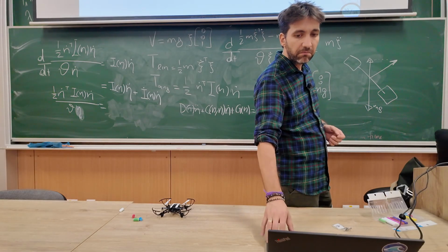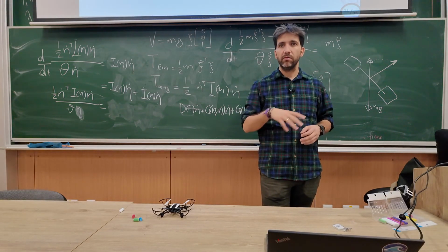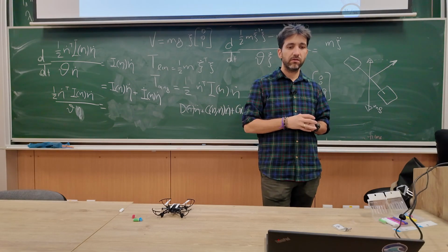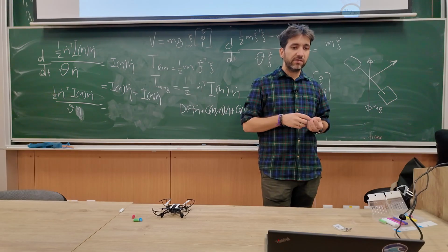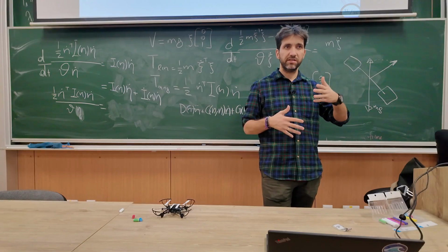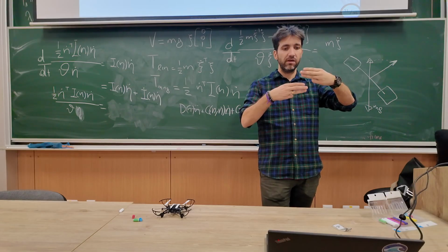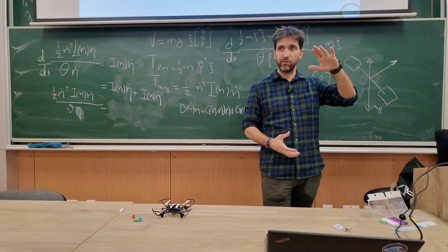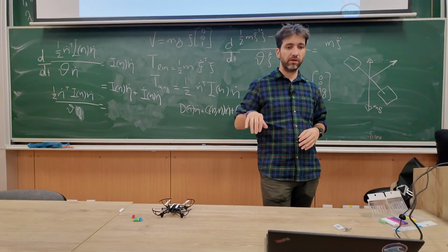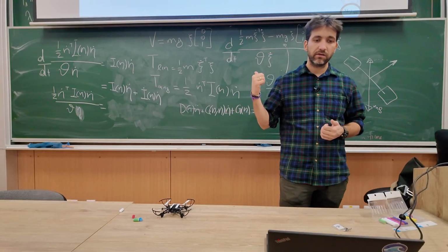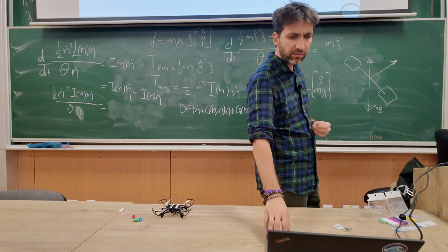So if we have A and B, we can calculate the state feedback gain. Maybe you remember one technique is pole placement or pole positioning. Our system has 12 states. So yeah, that's why I said it's not just Xi, because Xi is just the positions, but we have also the angles. So we have 3 positions, 3 angles, and then we have the velocities as well. So it's 12 states, and we have 4 inputs, W, PQR. So in the end, our state feedback will be a gain of 12 by 4, or 4 by 12, sorry.